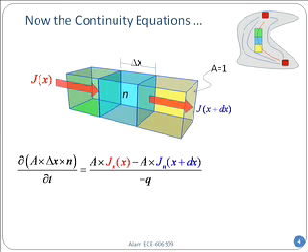Okay, so this is almost done. If I didn't have any other process, in fact, this would be the equation that tells me how many electrons are coming in and out. Now remember, these J sub n are the fluxes that are coming from the contact. These are drift and diffusion current. But of course, there is another current that we can also think of: if you shine light, that's a third source from which electrons and holes can come. So in that case, assume that the top yellow arrow, pointing downward, is light shining on that sample. So electrons are not coming from the contact, but coming from outside.